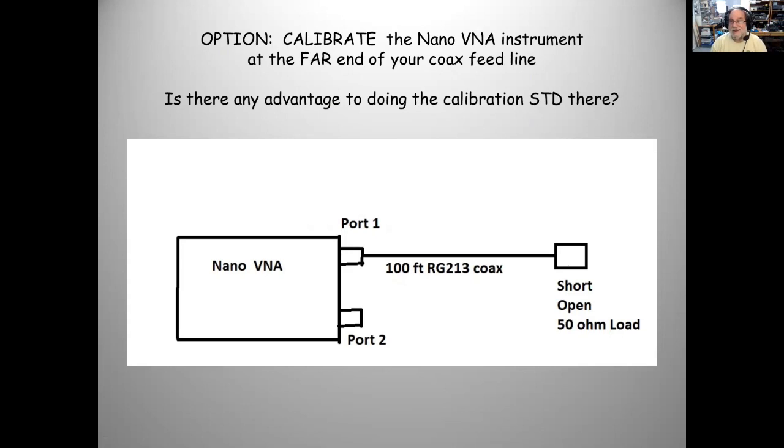Why? Do you see why? Does someone see why that's very useful? Whatever my NanoVNA measures, Smith chart, resistance, reactance, it's already taken into account my feed line if it's 100 feet. So what I measure on my NanoVNA is the same as if I climbed up to my antenna and hooked it right there and did the measurements, but I'm not going to do that. My other antenna analyzers aren't that smart. I thought, that's way cool.